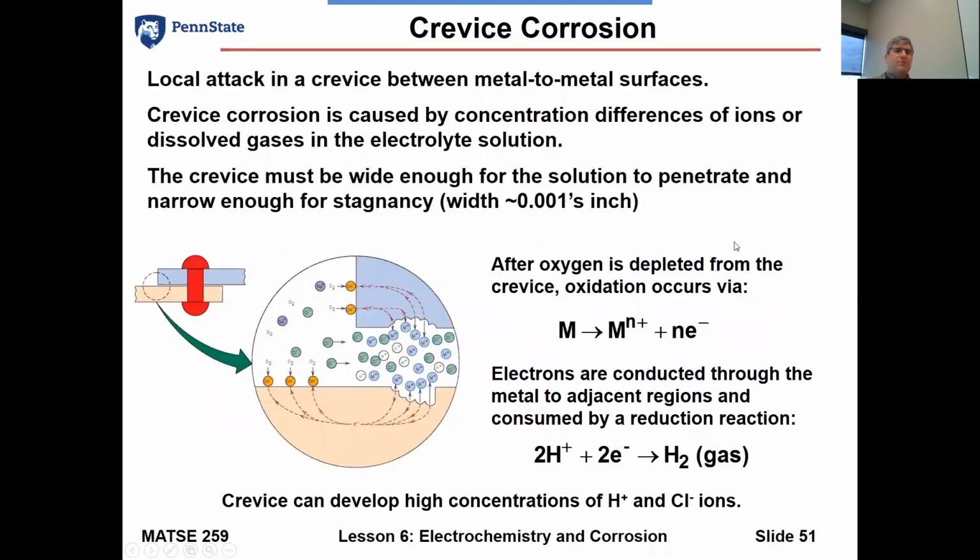The next one we want to really talk about is crevice corrosion. Crevice corrosion is a little bit more insidious. This is not something that we can see happening. And so in the schematic here that I've taken from the Callister textbook, what we can see is a lap joint around a rivet. Now, if we go back to lesson 0, or the introductory lesson of the course, I showed a fatigue failure in a couple of aircraft. Now, those aircraft are riveted skins. And so with the Aloha Airlines flight, you had some corrosion issues, and probably in all likelihood a crevice corrosion issue.